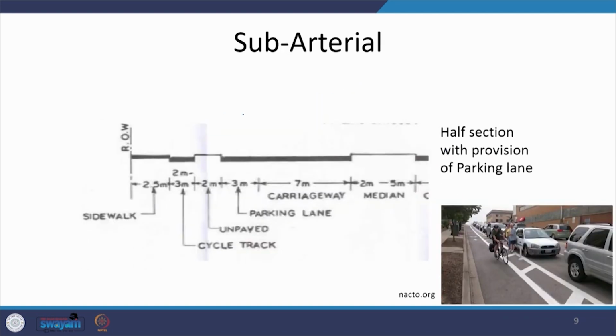This is a subarterial condition. In the case of subarterial condition, not much difference is going to be there as far as the specifications are concerned. You can have a cycle track, you can have a sidewalk or a footpath, there can be a verge which can be utilized for the provision of utilities, and there will be the carriageway which is being provided here. But apart from this carriageway, if we are allowing vehicles to park on this particular system under certain conditions of the traffic movement, then a parking lane can also be provided.